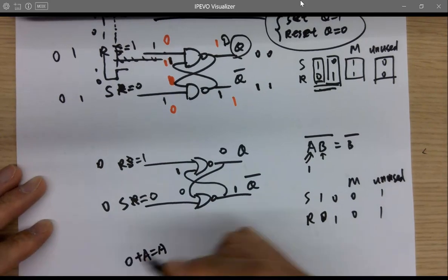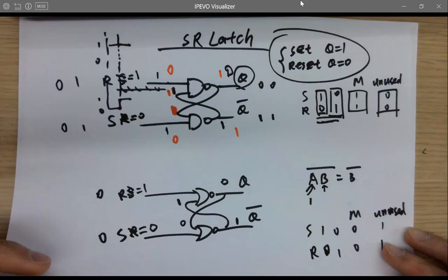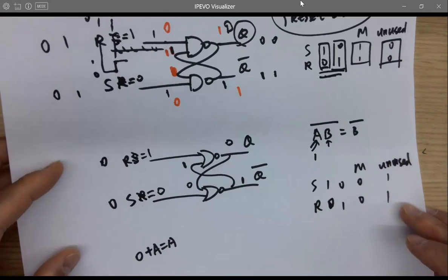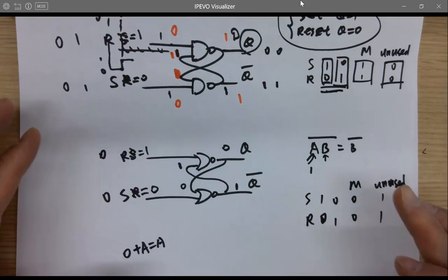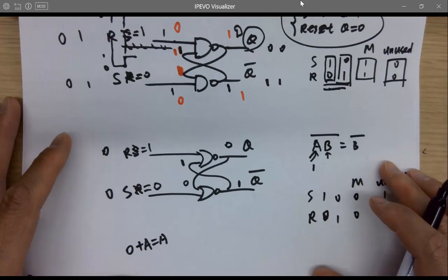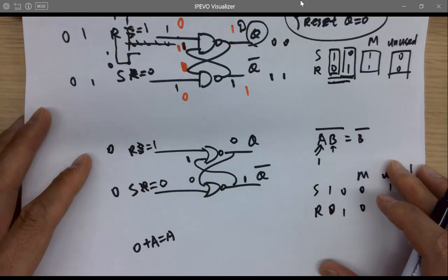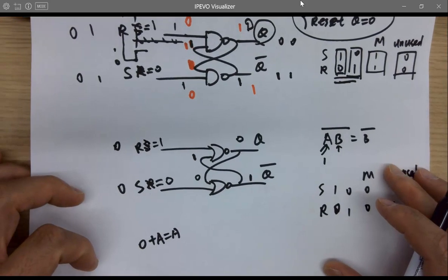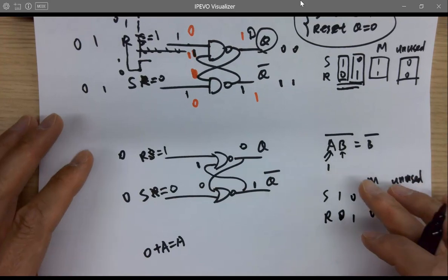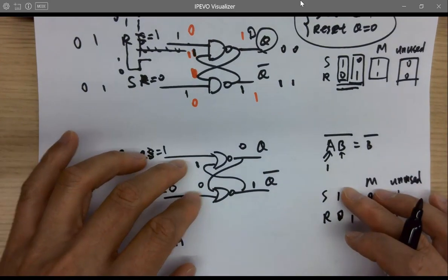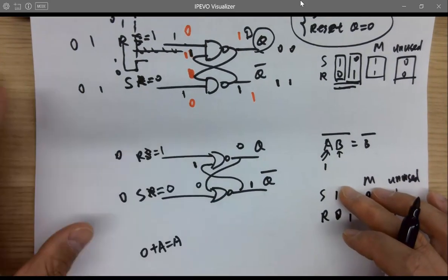Okay, so that's the SR latch. It's not just being used as a memory cell a lot of times, but also for a debounce circuit. You have using a debounce technique in software, right? Adding a little delay in there to debounce it. But you can also do a hardware debounce by using a latch.